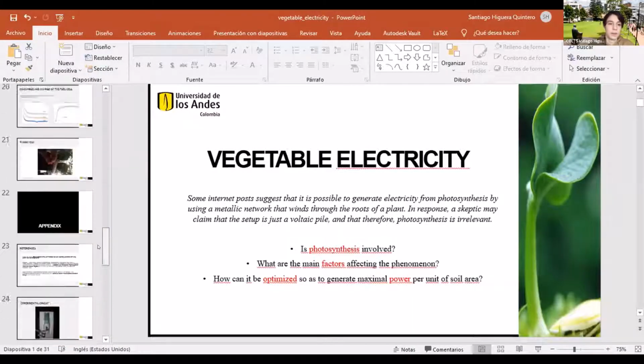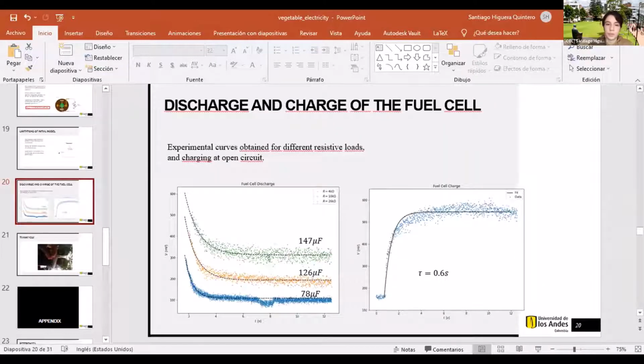So we actually found that although the model of the capacitor was done, you can observe that there is quite a flat ending of the voltage in time, right? So there is kind of a final stabilizing. So there seems not to be a moment where the capacitor fully discharges, rather a moment where there is an equilibrium between the creation of charges and a charge demand by the external load.